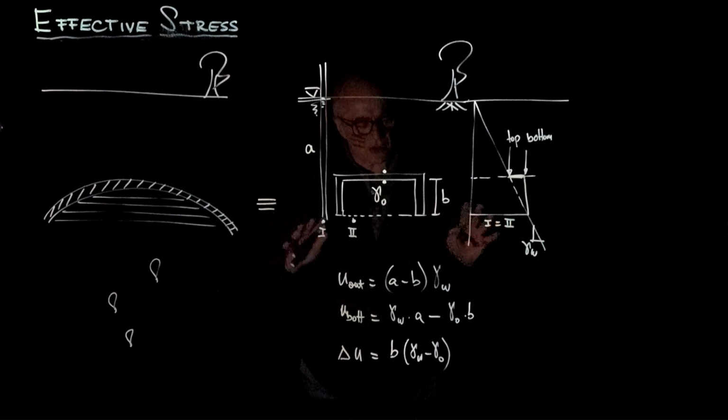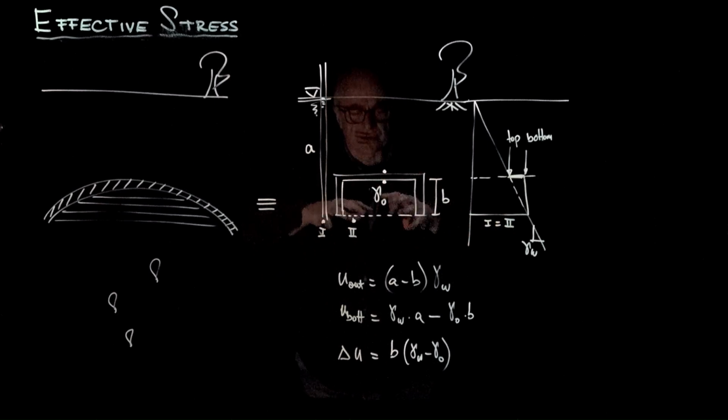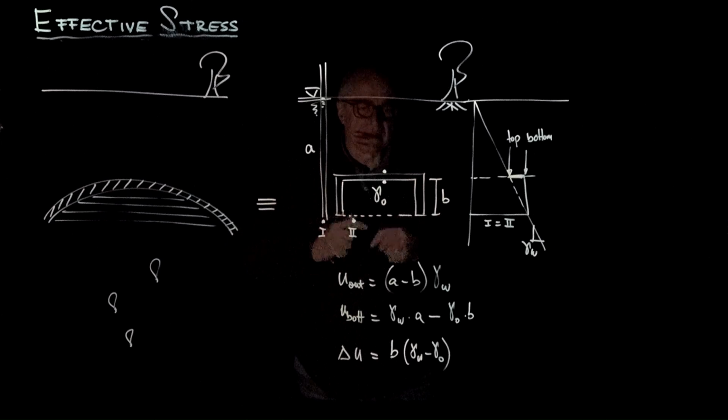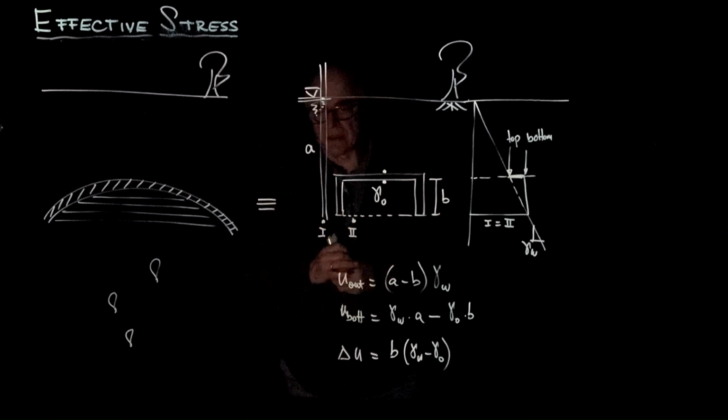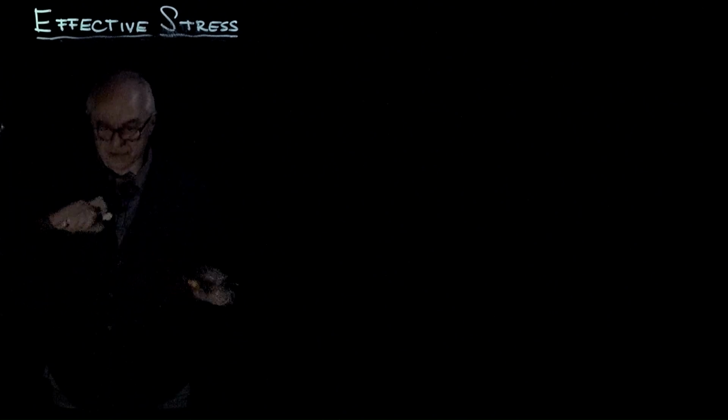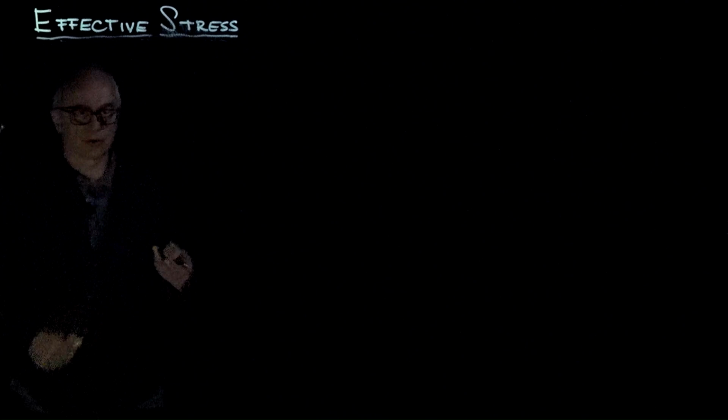It's not so easy because, as you can see, the reservoir formed and then oil began accumulating. So this is a case of unloading, and the loading and unloading history do affect the horizontal stress. And so this is not a true K-naught case, and we will return to that when we look at state of stresses in soils. The last couple of examples bring other important cases that are of extreme relevance to the geotechnical field, from the near surface to petroleum geomechanics and deep boreholes.